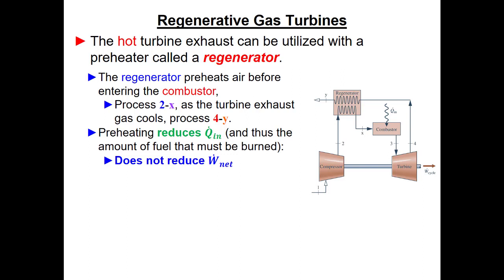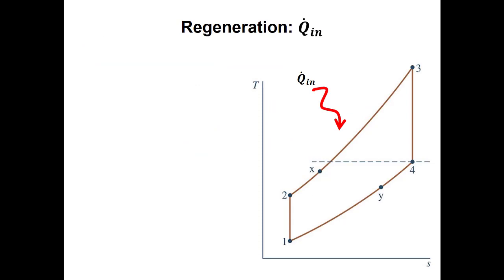bringing air into the house that's cold because it's cold outside, you can preheat that air. You can do the same thing in the summer when your air conditioner is running, where you're blowing out exhaust from your house, which is cold air, and it can pass hot air as it comes in to kind of pre-cool that coming in. So how does a regenerator work?